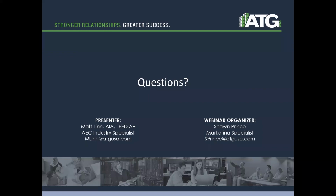Is there any way in the DIM checker to see which dimension style is used, in particular looking at rounding values? So for that, Chad, I would consider looking at the type swapper to find those that you want and replace them with what you're looking for. So in DIM checker, by the name, it's simply checking the values themselves. It doesn't actually change them for anything. So I hope that helps.